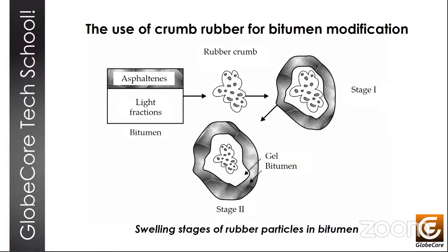The traditional technology for making a homogeneous RBB, meaning rubber bitumen binder, provides for mechanical mixing of rubber crumb from 5 to 30% by weight with bitumen. That could be tar, recycled asphalt, or any mixture of the above. The temperature of the process is 150 to 250 centigrade, and the time it takes to mix is about 30 minutes to 24 hours. And it's done in the presence of surfactants or plasticizers.